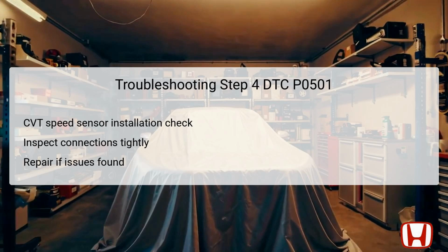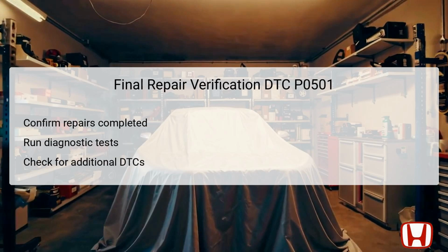Final verification of repairs is critical after addressing the symptoms of DTC P0501. Start by confirming that all necessary repairs or replacements have been thoroughly completed. It's crucial to run another set of diagnostic tests using the HDS to check if the same DTC or any new codes appear.